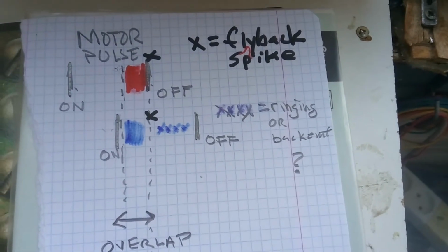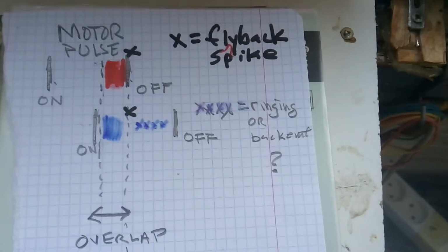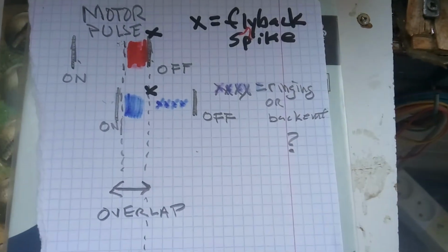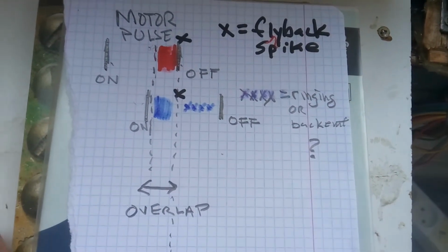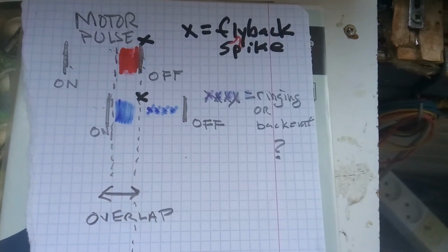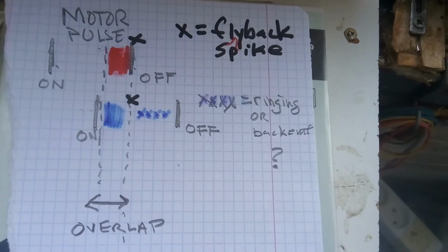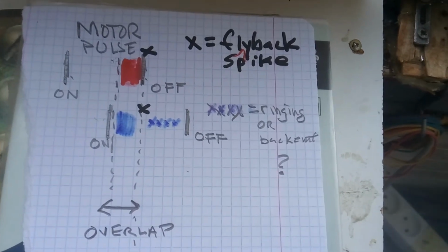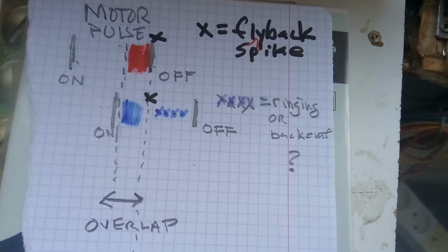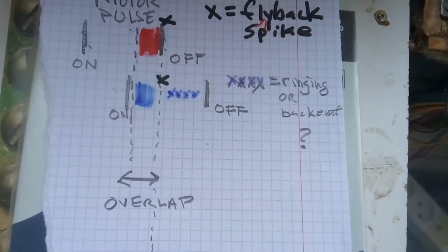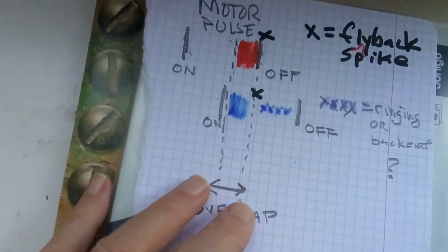Okay, I want to make sure everybody knows what I'm doing here. It has nothing to do with Lenz's law of generator coils being swept by magnets. This is all about recovering the flyback spike, the back EMF of a DC motor coil pulse.